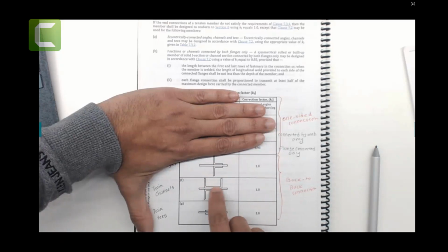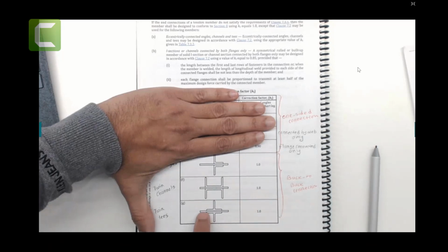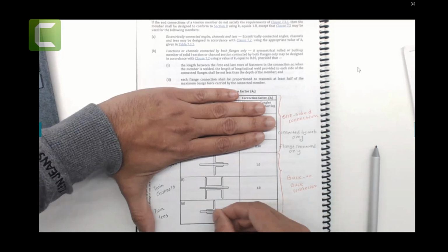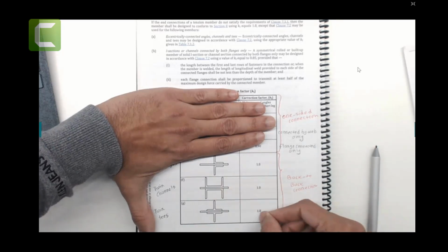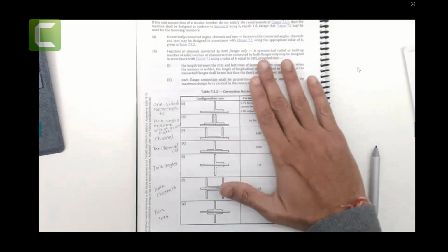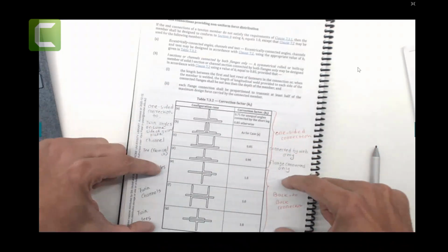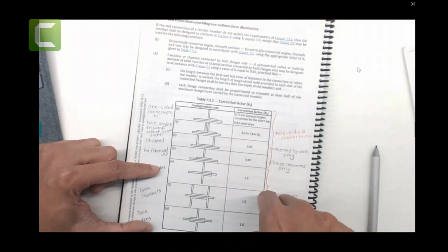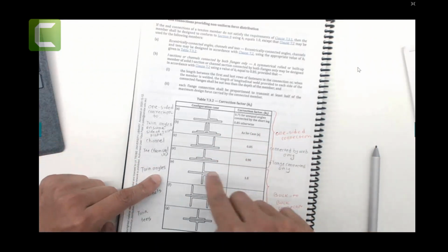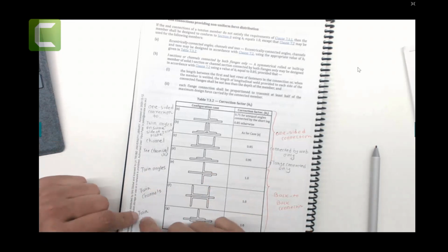This is the flange. The web is connected, the long member connected, then you have KT equal to 1. This is a plate that we're not designing. Let's say this is an I-beam and this is half an I-beam, your KT equals 1. So this is how I look at the tables. Just look at these two. It is back-to-back connections. Back-to-back connections, KT equal to 1, uniform stresses, like twin angles, twin channels, twin T's.